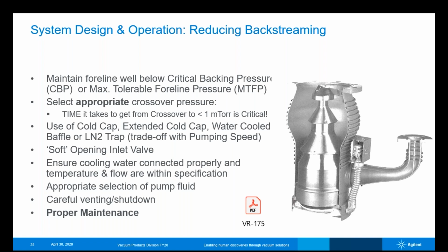Speaking of oil, we need to choose appropriate pumping fluids based on the vacuum performance that we require, but also based on what kind of backstreaming we can tolerate, and what our chemical process is, what we're actually going to be pumping away as a pumped media. As we know, the different gas species that we're trying to pump could break down the fluids in different ways. So we need to take all those things into consideration.